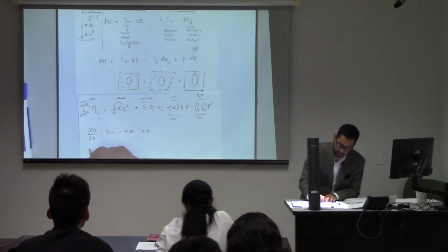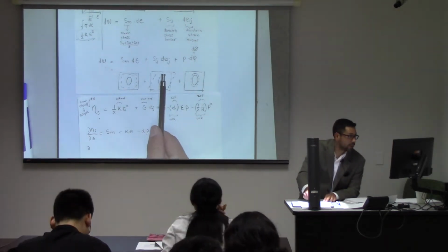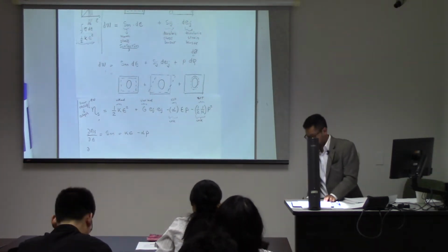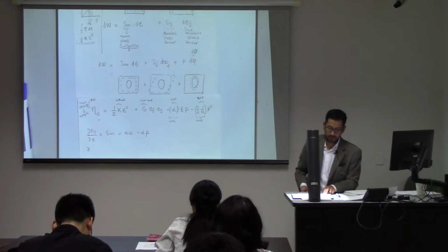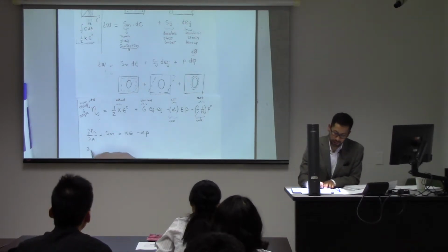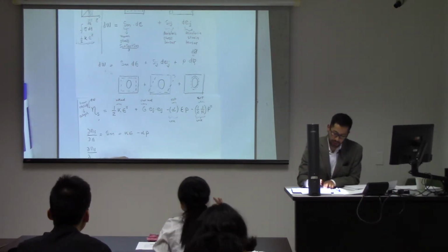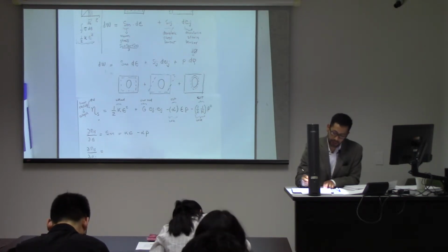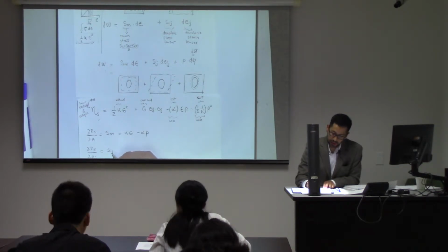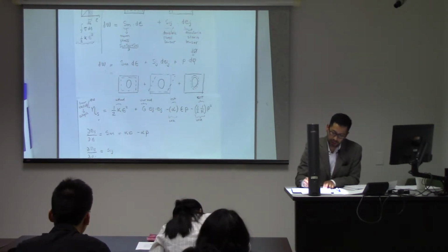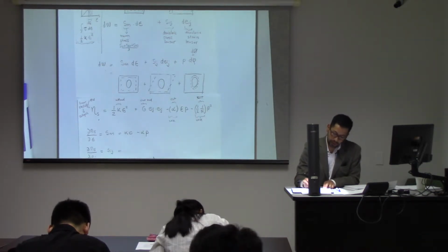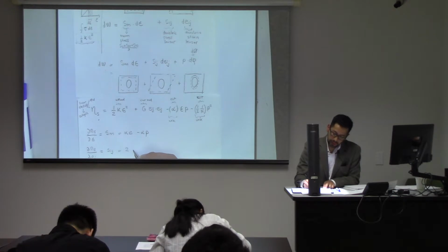And if I take, similar to this one or to that term over there, the derivative of the free energy of the solid with respect to the shear strains, I'm just going to get the shear stress, which in this case is 2 times G times the shear strain.